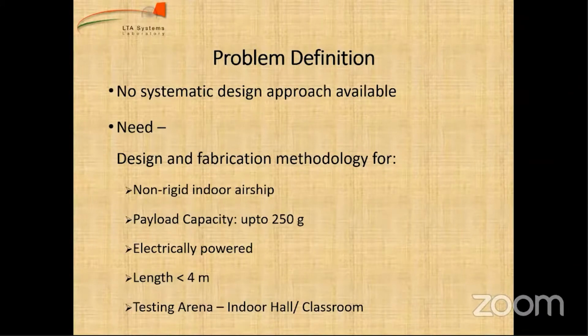And the need of this design methodology is as follows. We have to design a non-rigid indoor airship with a payload capacity of up to 250 grams. It should be electrically powered with a length less than 4 meters, and the testing area should be roughly an auditorium indoor. I'm saying that this is not something we must stick to, but it is something we have brought upon ourselves so that we discipline our design to satisfy these requirements.